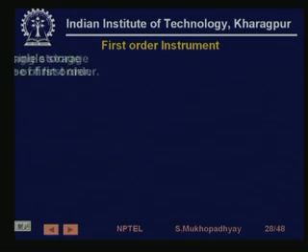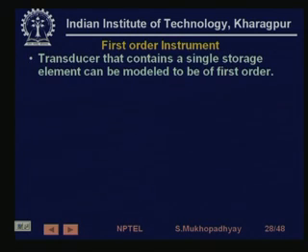On the other hand, there are some kinds of instruments where if the input changes suddenly, the output cannot change suddenly. The output takes some time to rise. For example, let's take temperature measuring instruments. For example, a thermocouple. Actually, a thermocouple, as you will see, is not bare wherever it is making the measurement of the temperature. Maybe it's steam. Then the bare thermocouple is actually not inserted into the steam, because that will damage the sensor. It will degrade fast. So it is actually put inside a tube. So you can imagine that even if there is a temperature change outside that tube, which is called a thermo well, it's a tube, and inside that you have the thermocouple.